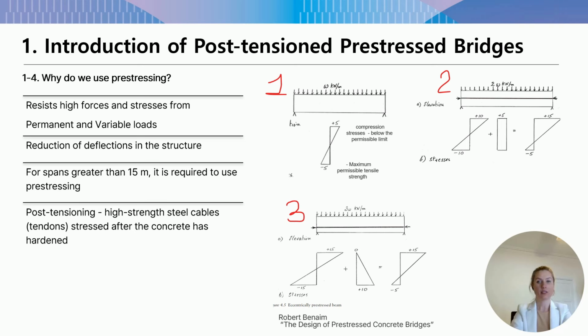The pre-stressing is designed to remove the tensile stresses in concrete, since this material doesn't work well in tension, and to reduce the deflection of the structure. Note that in a simply reinforced beam without pre-stressing, the concrete in the tensile zone is just to hold the steel in place. And this material in this zone adds more weight, but it does not use the strength of this material in any way.